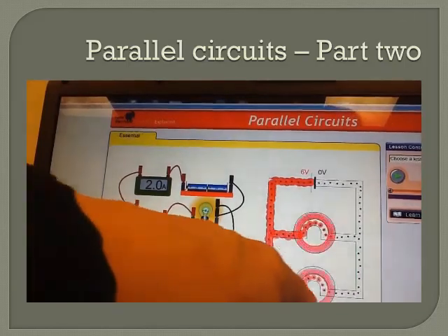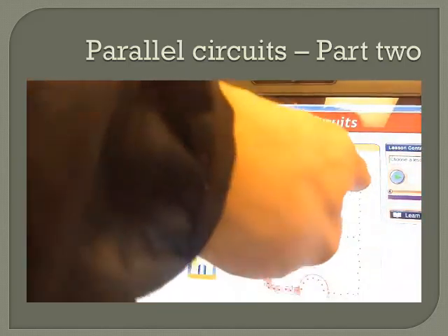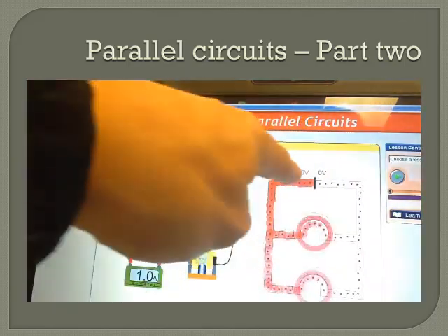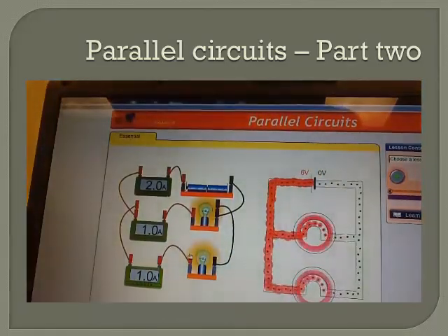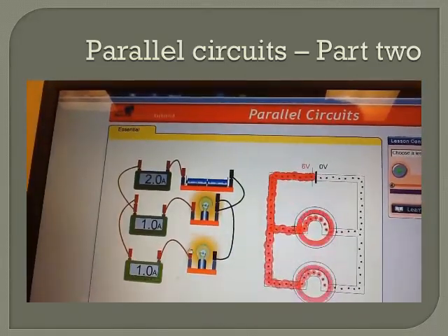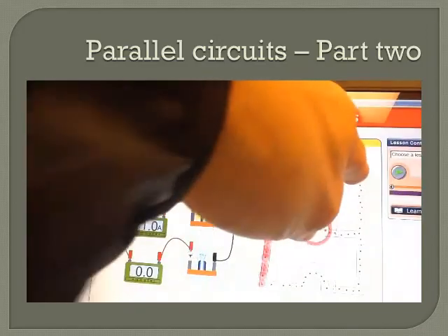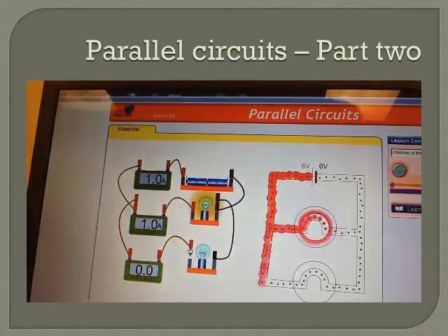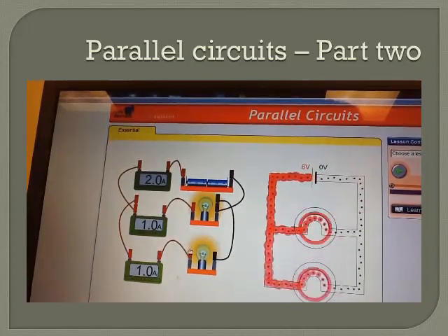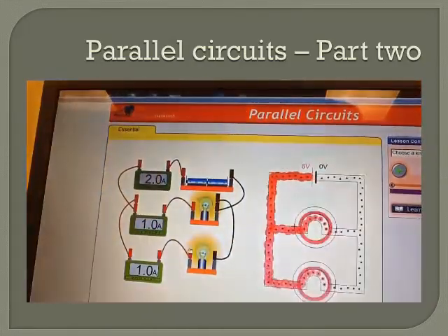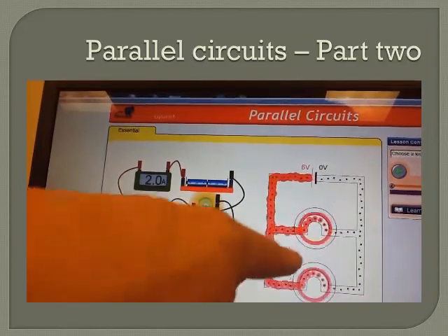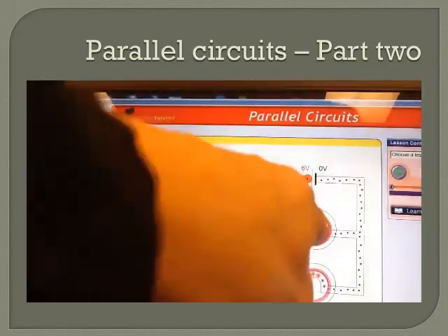First of all, I do have charges moving through this second loop now. Notice how the flow through my battery has changed when I am connected versus not connected. Notice that I've got a difference. They're flowing slower right now than when they're connected. Now I've got more flow going through the battery, right? Well, why is that? It's because now both of my branches are demanding current.